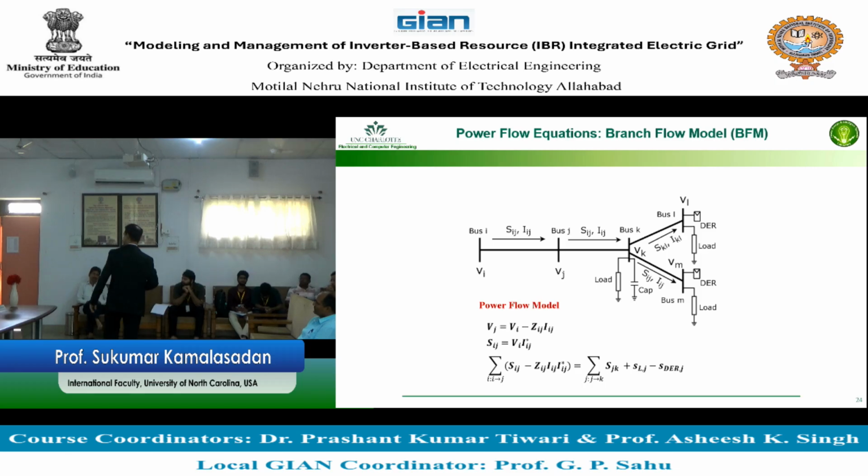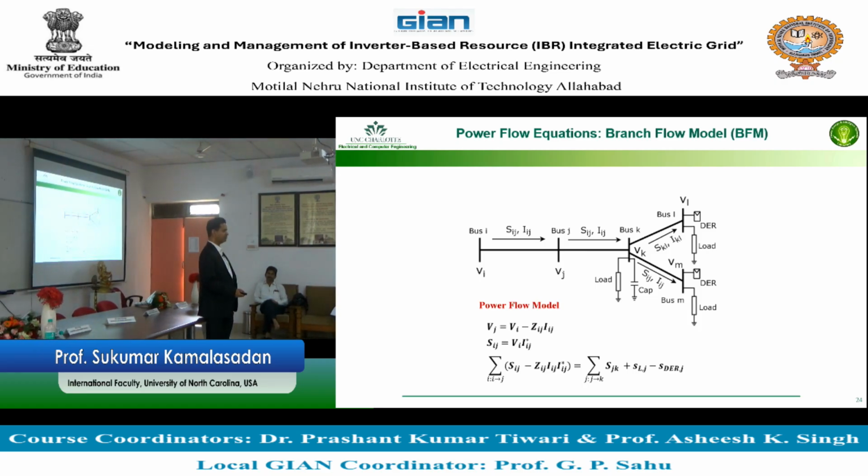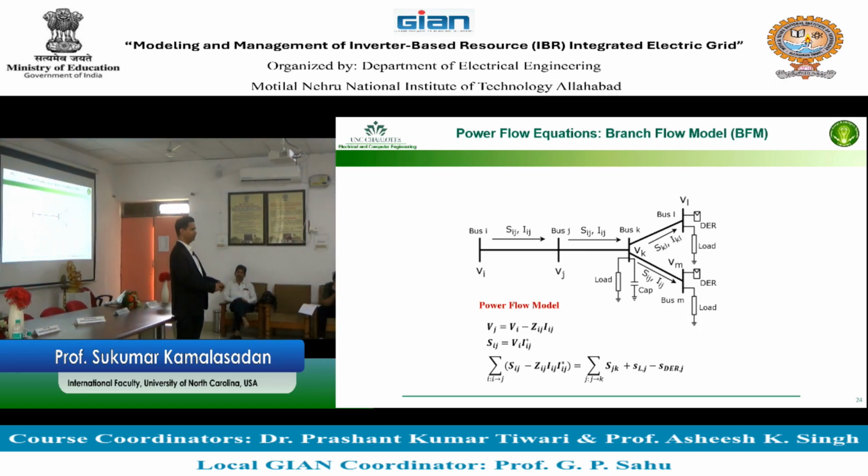The other part is you see this VI conjugate, right? What is VI conjugate? Let's assume that you delete all the I and put V instead. So I equals V divided by Z. So VI conjugate is V square divided by Z. Then it becomes non-linear. But if you keep the I there and there is no complex connection, two independent variables, not dependent on each other, then you can treat them separately and write that separately.